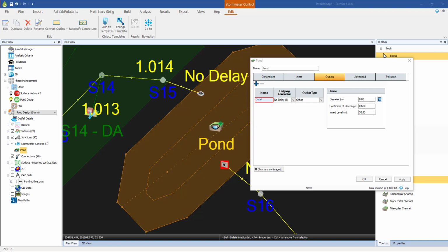Okay, so if we now go into the calculator, the design depth is 1.675 meters and the design flow is 16.1 litres a second. We've got this coefficient of discharge, fairly standard for an orifice, but it's going to give us a diameter of 0.077, 77 millimeters.